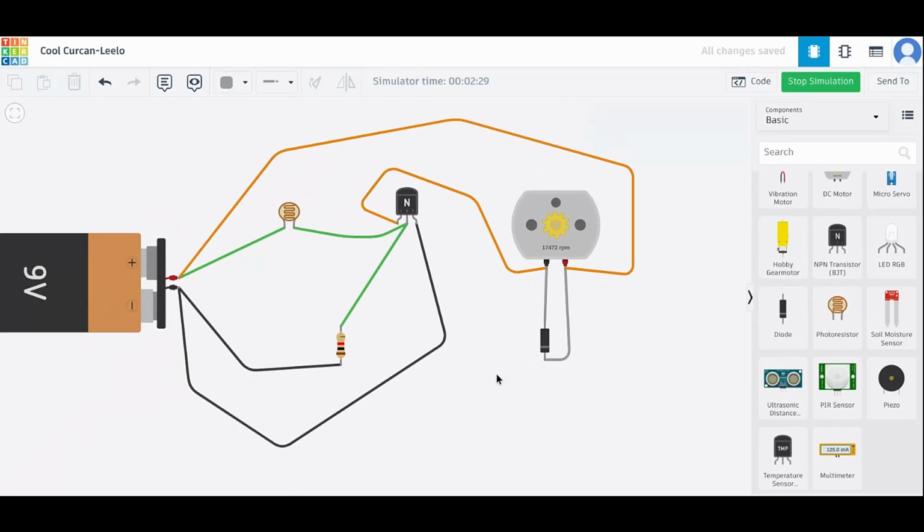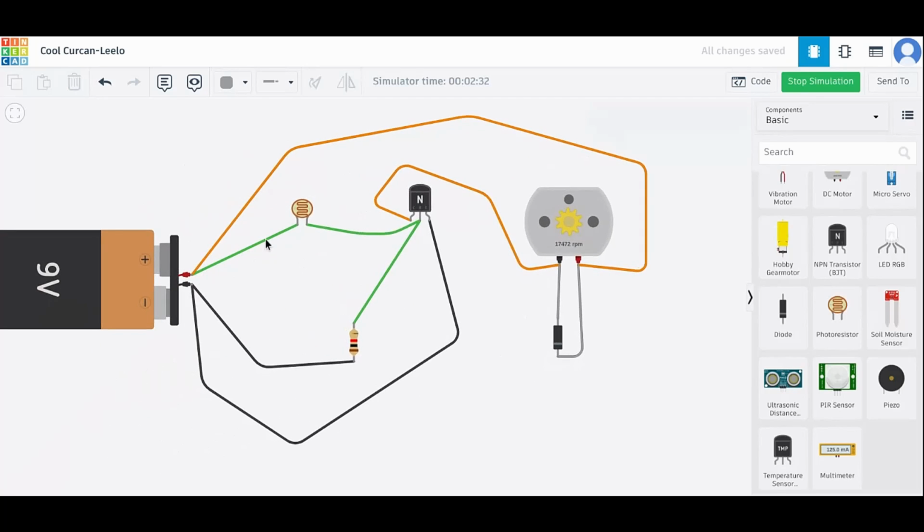There are a couple of ways to do that. You can notice I do have a potentiometer setup here. The green loop is a potentiometer setup. If you put a potentiometer, you'll have to slightly modify that. But the idea is you can take the potentiometer output and then map it to the extent you want to turn the circuit on and off. The beauty is that the voltage is always, in this case, 9 volts across the motor, barring some minor changes across the transistor.